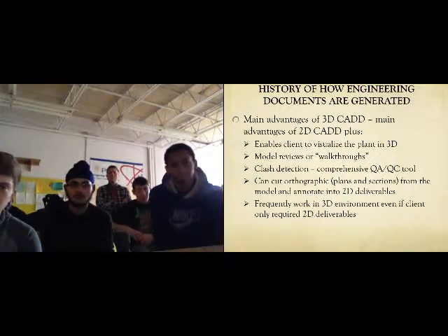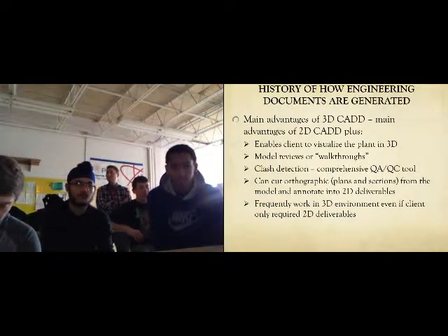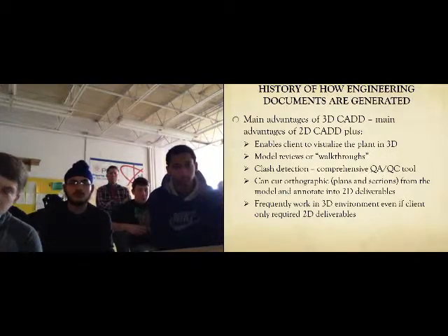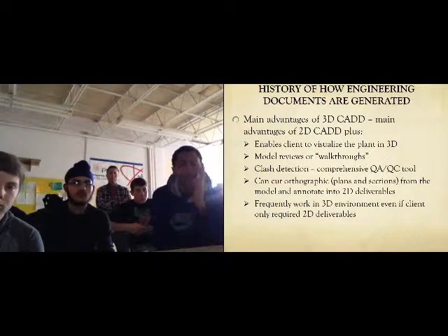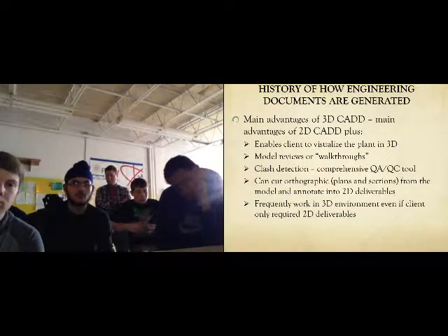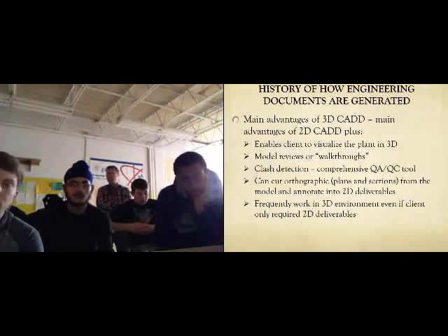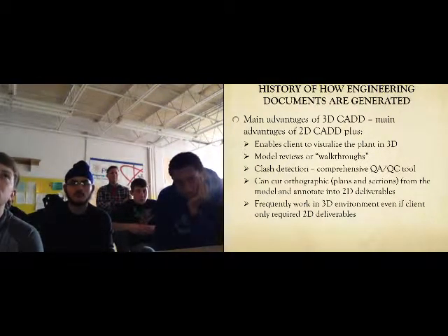And then what you do is you go to each one of them in the model and you look. Now, if you mounted some pipe to structural steel, that's an acceptable clash. So you just go past that one. Sometimes what you'll find is you did make a mistake and a piece of pipe runs straight through a platform. So what you have to do is reroute the pipe, or you have to change the platform. Now, why is that important? It's very simple to do on your computer. Rerouting a pipe is easy to do. Let's say you missed that.